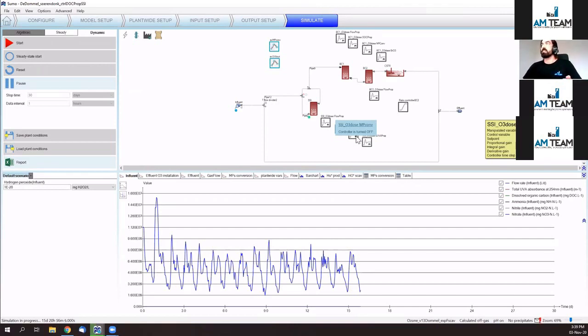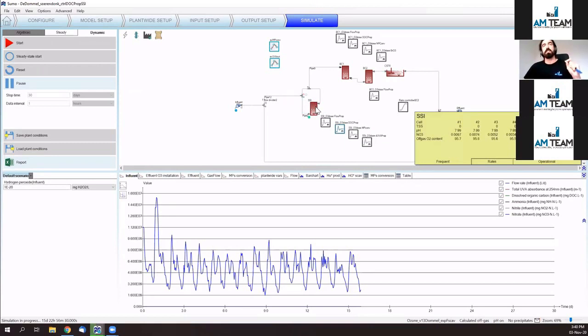We can look at it later, basing your actual dose on a specific micropollutant to be sure to be within the legislation boundaries. And also another one, the UVA proportional controller, so ensuring that part of the UVA fraction is knocked down, and basing your ozone injection on that. So after the side stream injection, after injecting your needed ozone, then you re-enter the mainstream and you let the reactions happen in your volumes and the rest of your installation: ozone, radicals, micropollutant reactions, bromate, and so on, until you discharge.